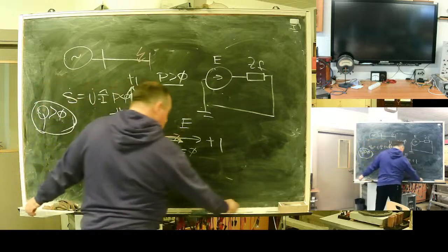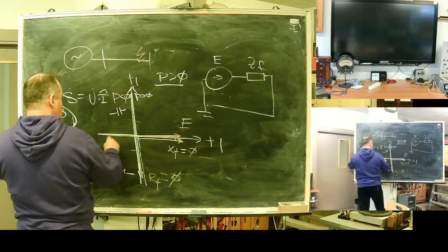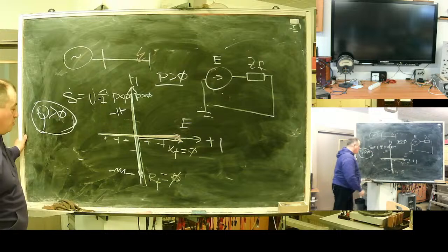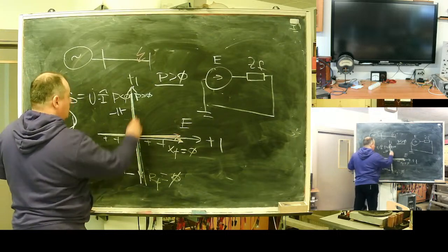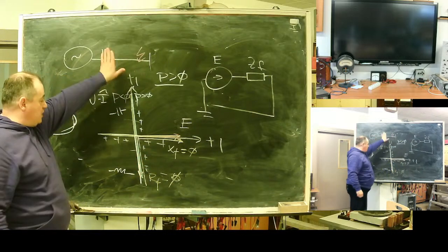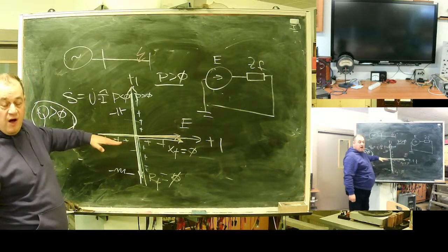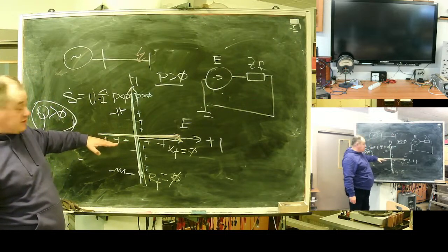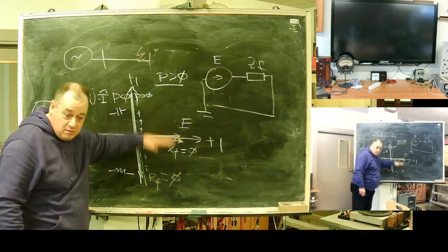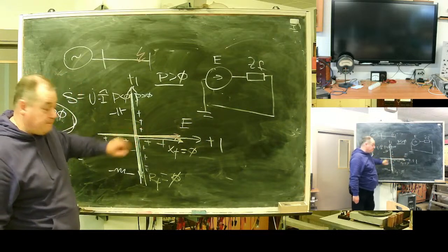This will give us a characteristic like this. For the active power, I will mark with a plus operation. Operation allowed in this area. If we take a Var meter, another meter of reactive power, it will produce a characteristic this way. Also, in this area, not the best one.